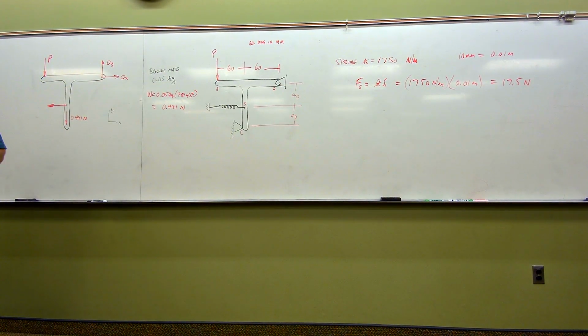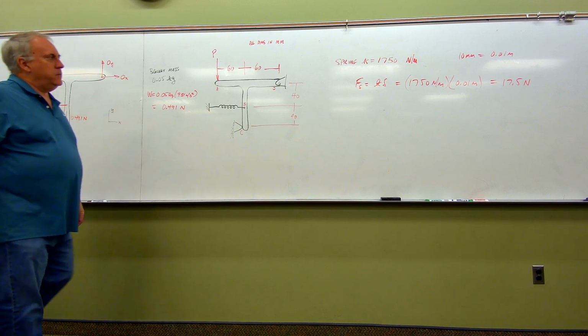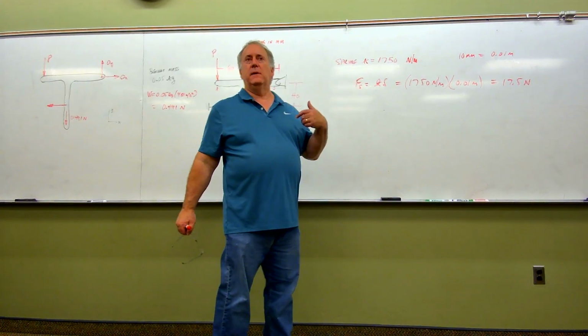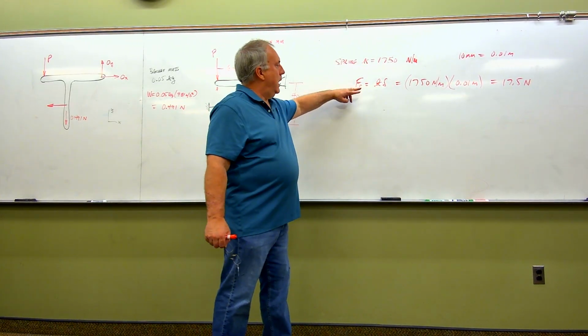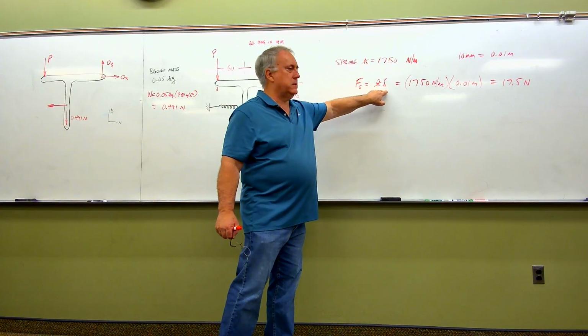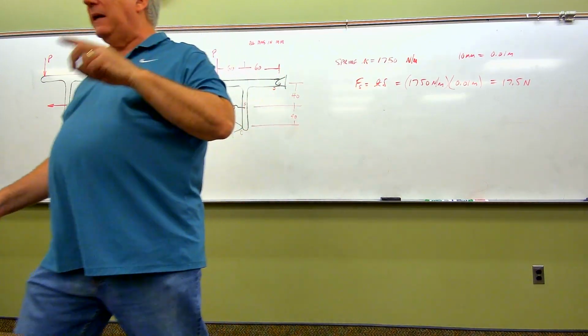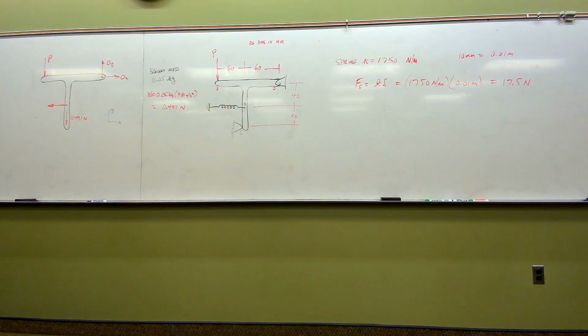Now, I'm pausing here, because I mentioned to you in the previous that the authors kind of lied to you a little bit here. And this is just an FYI, this will become more important to you in later courses like machine design. The force of the spring, K delta, that is correct whenever we're dealing with a compression spring. It's not correct for a tension spring.